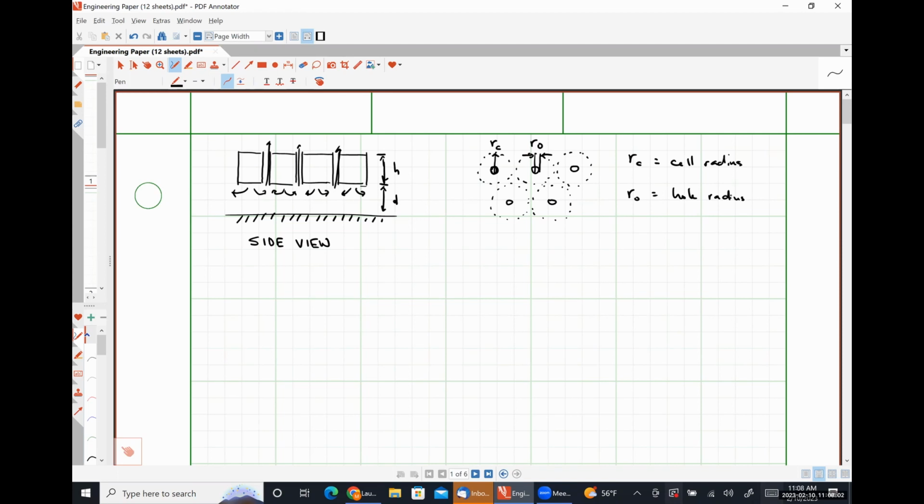Okay, so the purpose of these holes is to not allow the air to compress by giving it more pathways to escape through. So we should not have a spring constant for these situations, because the entire purpose is to not allow for compression, right? We are going to have a damping coefficient, and our damping coefficient to some extent is going to depend on the thickness of the plate.